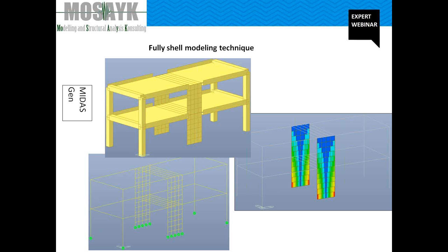It is important to select thin shell element, because thin shell is based on the Kirchhoff theory, and this means that we have a thickness of centimeters and an area of the panel of square meters. So the panel is thin.